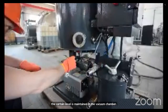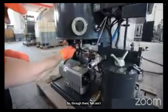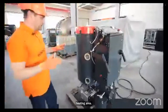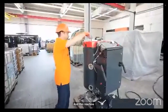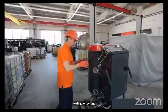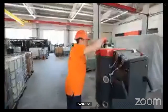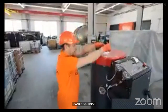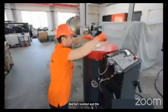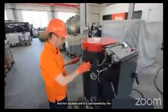So, through the solenoid valve, oil goes into the heating area. In this machine, the heating vessel and vacuum chamber are combined in one module. So, inside, the heater is located, and it is surrounded by the volume of the vacuum chamber.